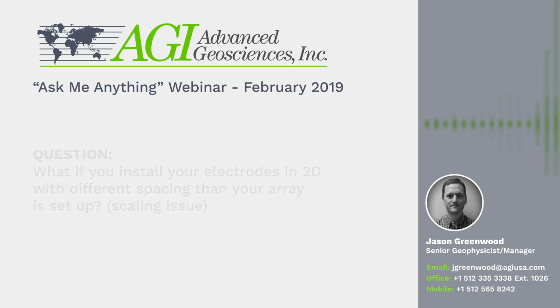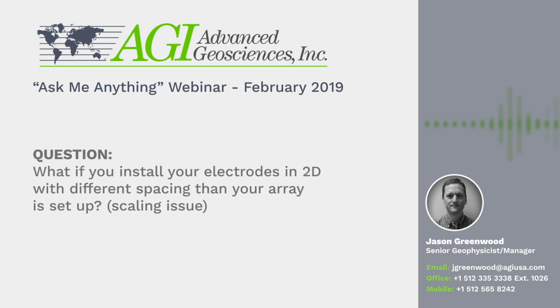So with 2D, it is possible to rescale it. Now, in 3D, that's not the case because it's much more complex. You have issues where certain dipole combinations should not be collected if they're beyond a certain distance. So with 3D, you don't use scaling at all. That's a whole other set of questions. But for 2D, we can fix these scaling issues. Let me show you how to do that.